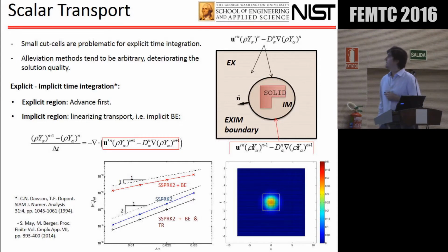Now, these small cut cells that we might end up with, because we have a Cartesian mesh, let's say you're running FDS, you have your Cartesian mesh, you put your immersed object there, and you might have cut cells or polyhedra of different sizes, and some might be really, really small. And people who have used FDS and increase the number of cells in the calculation see that the time step becomes smaller.